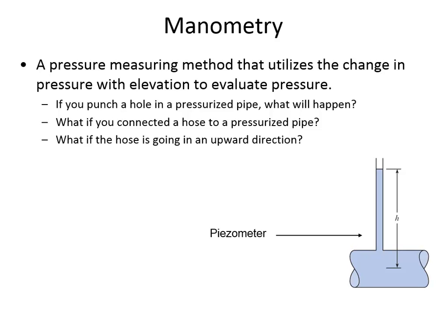If you've got a really highly pressurized water pipe, then it'll rise tall. Like 500 kPa, the delta H for that is going to be around 50 meters, 52 meters. Because if you've got 500 kilonewtons per meter squared and 9.81 kilonewtons per meter cubed, then the delta H will be, is it 52? Anyone with a calculator handy? How much? 51 meters is how high the water level will rise to.